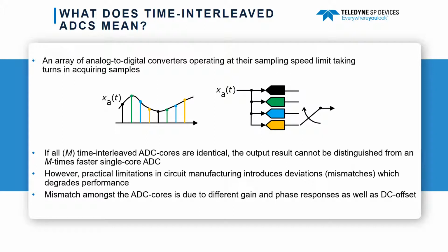This makes the time-interleaved system suitable only for oversampled applications for the use of a large number of ADCs in the array. Achieving sufficient input bandwidths in the time-interleaved ADC structure is typically accomplished by using amplifiers or sample-and-hold circuitry in the front-end design.